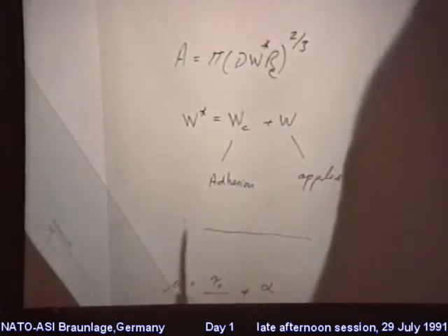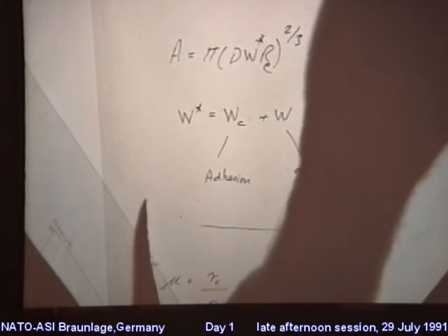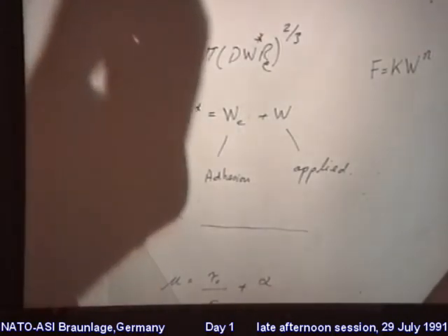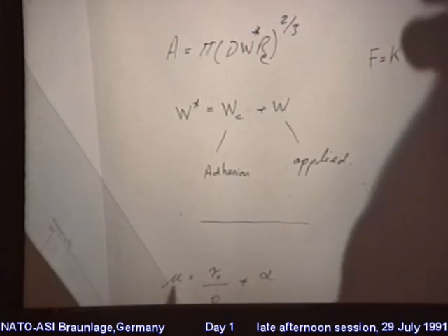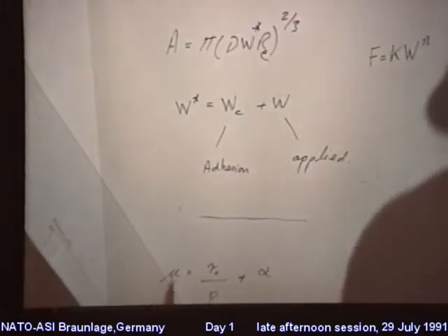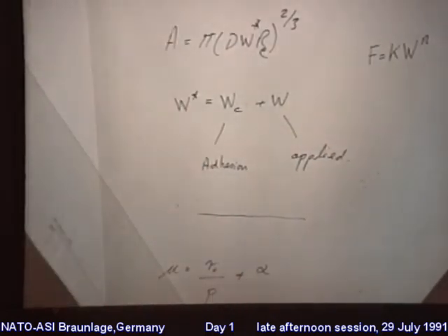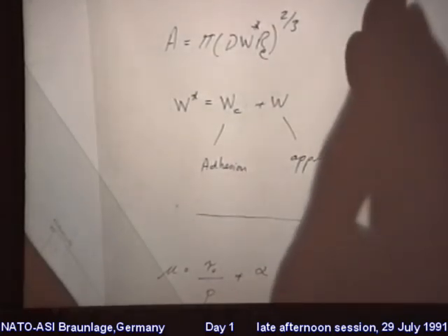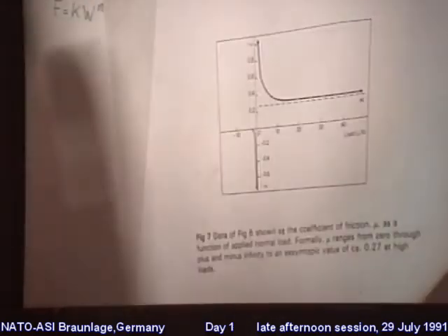There's the contact configuration. You can apply the load by bending the fibre, and of course if you move this fibre backwards and forwards you can displace the fibre. Simple beam equations will allow you to compute the friction, or indeed if you measure the critical separation with respect to that axis as a function of L cubed, you can get the autoadhesive load, W_C, that you mentioned. And I used Johnson, Kendall and Roberts there, and I've shown this scaling argument. Now, the reason I bring that up is that you can actually slide under negative load, and you can see the load is negative there.